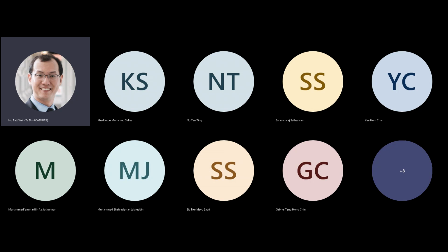If you bring it into a region with higher temperature, let's say you put it into an oven at 100 degrees Celsius, that just means you're putting it in an environment where there's more energy available to be absorbed by the electrons. Therefore there'll be many more electrons that have sufficient energy to escape the capture of these silicon atoms, and they can be moving around, and they are known as free carriers. So there is a relationship between the temperature and the available free carriers in the semiconductor device.